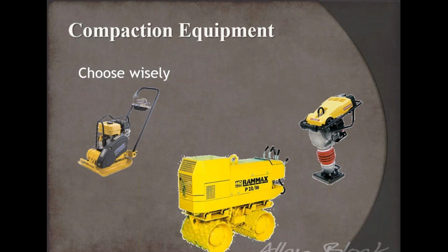So great piece of equipment when you're talking about those fine aggregate or fine grained materials and cohesive soils. Then on the right-hand side, we've got that little jumping jack, I always call them. Great compaction piece of equipment, don't get me wrong, but let's face it, we're trying to keep the block pretty level. And so you might be able to use something like this in the foundation area, but behind the block, it gets to be a little bit problematic because they're pretty violent and you lose control of that a little bit, and all of a sudden you're moving the block. So we tend to not use those or recommend those for compaction activities behind the block for that reason.